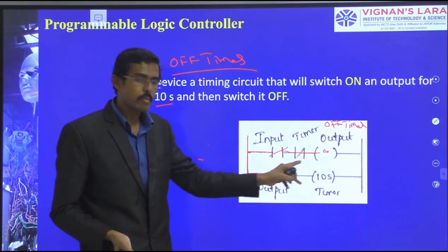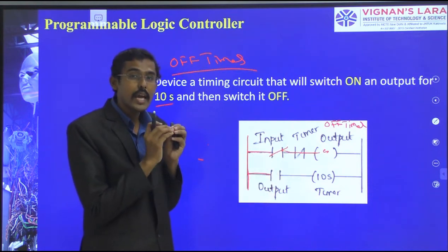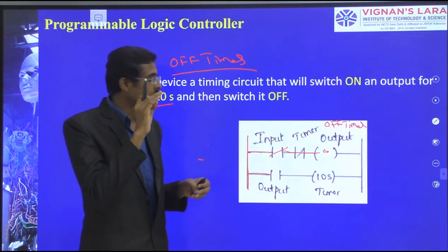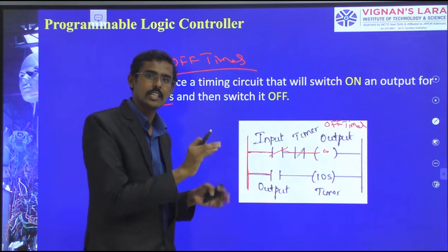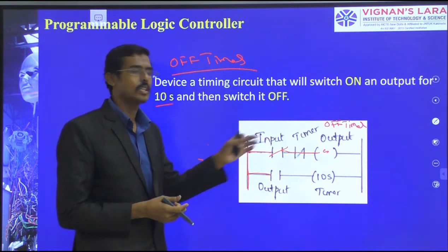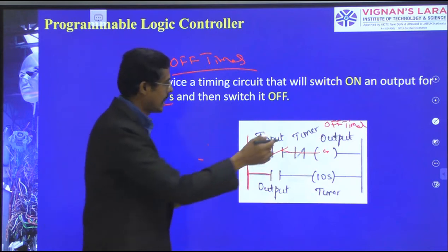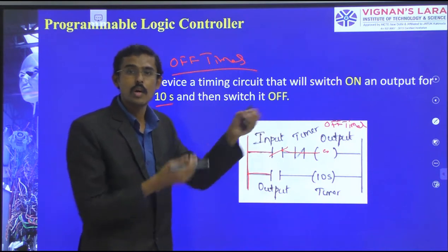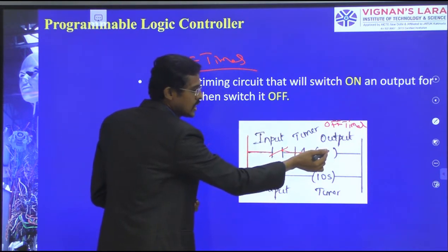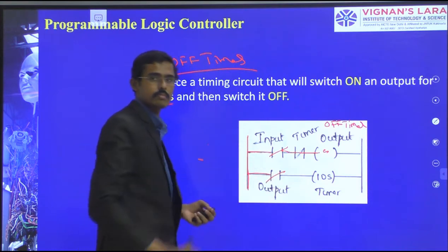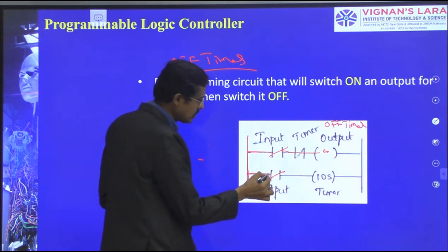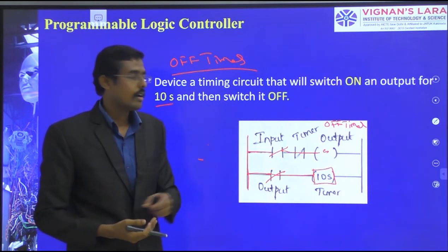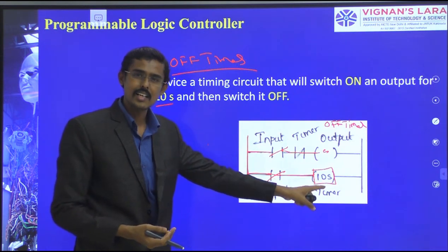In the middle you can see I have made a brake contact in the name of timer. What does it mean? When that one is detected or sensed, it is going to break the contact. So that is the point there. When it is detected, I have kept the output switched on. By the program, it should be off after 10 seconds. When the output is given, this output is taken here as an input, and therefore it gives the connection to the timer for 10 seconds.